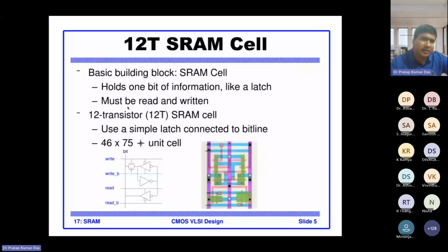So now let's see, what do you mean by SRAM cell, right? SRAM is static RAM. So if you see here, what happens is you have a back-to-back inverter circuit, right? And then, for example, to write, you have a signal here, and the opposite of that is write bar, and read bar, right? You get it? So how many transistors will be there here? 2 plus how many here? 4. Okay. So 2 plus 4 plus 2 plus 4, right? 4 plus 8 is 12. Why 4? Because you have this enable one, right?